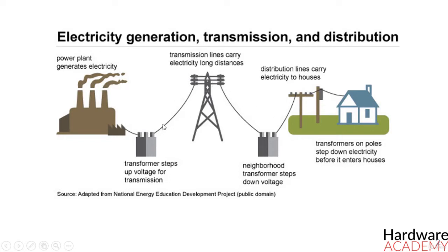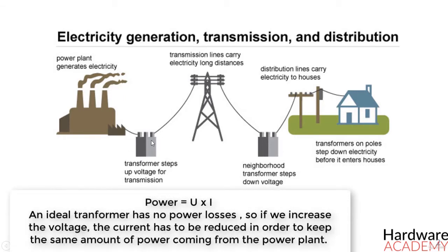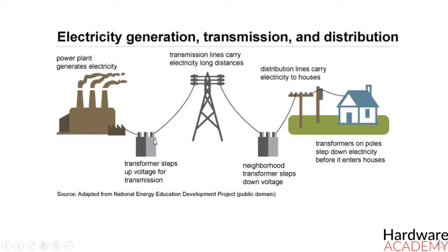If you were wondering why we have to transform the voltage coming from the power plant to a higher voltage, which is done by the step-up transformer here, the reason is that higher distribution voltages imply lower currents for the same power, and therefore lower power losses along the network grid of cables. These higher AC transmission voltages can then be reduced to a much lower, safer and usable voltage level where it can be used to supply electrical equipment in our homes and workplaces, and all this is possible thanks to the basic voltage transformer.